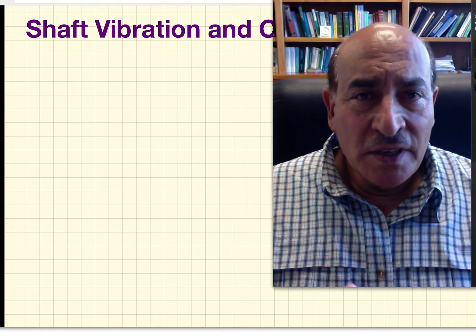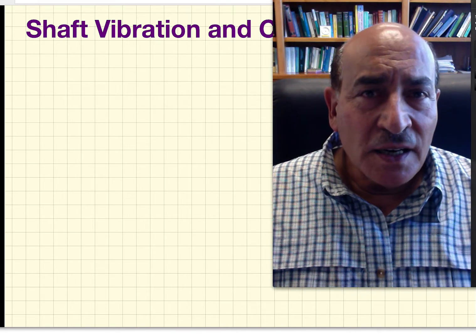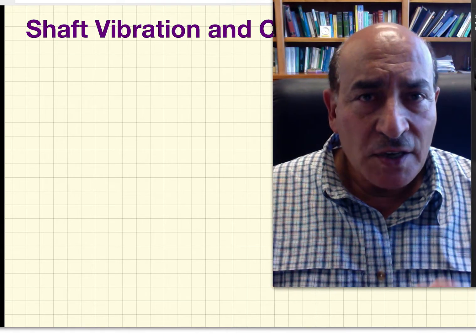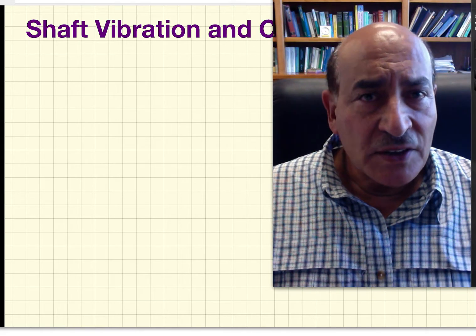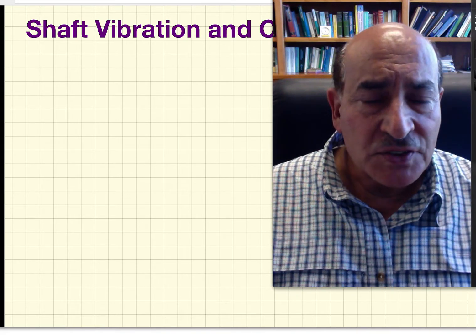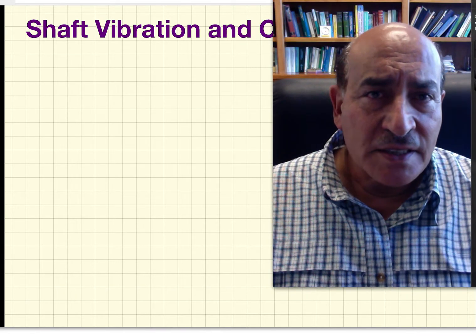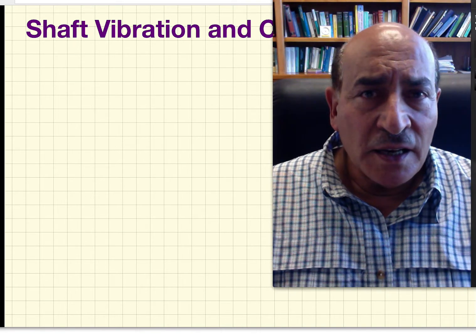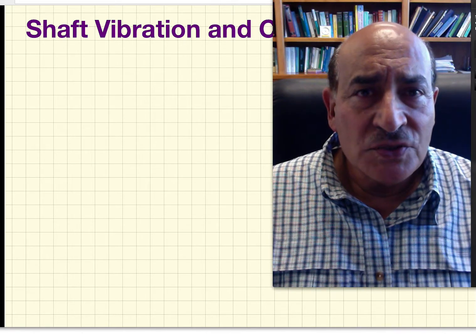As we know, the shaft as it rotates is not perfectly centered along the axis, and if we have any deviation from complete symmetry, a shaft can oscillate and induce dangerous vibrations. Not only that, but if we have masses attached to the shaft, such as gears and pulleys and other devices, then you will have concentrated masses, nearly concentrated masses, that can also induce unnecessary vibrations.